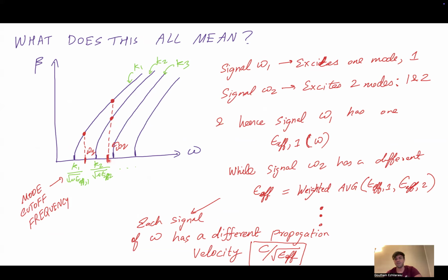In general, when you design a waveguide, you always want the transmitter to excite only the fundamental mode of the waveguide, because it's very difficult to match your transmission line for all different mode configurations, since you typically match it for the fundamental mode. If you end up exciting higher order modes, it's going to create much more reflections and more issues in signal integrity. So when you design your waveguide, you always want to design it so that, up to the frequency range of operation, it only excites the fundamental mode, typically the TEM mode.